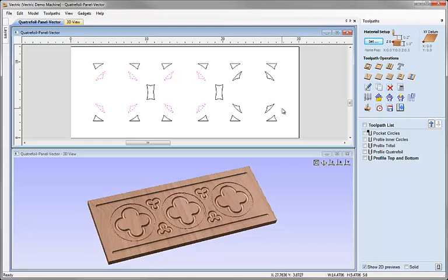So it doesn't need to be completely enclosed, it just needs to fall partly within the selection box. So if I click here and drag up to the left, then I don't need to completely enclose these, I just need to partially touch them. I can let go and they'll be added to that selection as well. So different situations might require you to use those different things depending what other vectors might be around the ones you're trying to select. It's good to understand those, and it's worth having a little practice to really get an understanding of what they do.